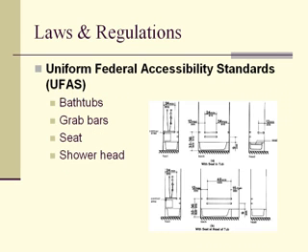Okay, another element that is necessary in these accessible bathrooms is to have either a bathtub or a shower. Looking at these bathtubs, these are some of the specific requirements. Number one, they have to have grab bars. As you can see from the diagrams, there's a grab bar on the control wall, one on the back wall, and even one on the head wall, basically on all three walls.